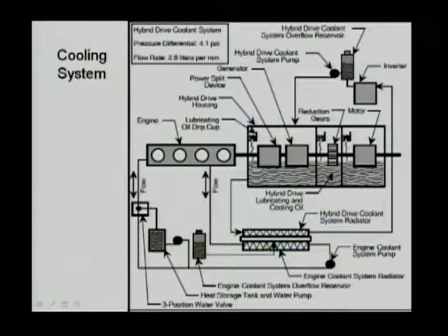But just above the engine coolant radiator, there's another radiator, even though they are mounted at the same place, but it is a separate radiator. And if you follow the arrow pointer directions, coming out of the radiator, the liquid will go through a pipe to the inverter on the top right corner. So the liquid goes to the power electronics to cool the power electronics first. So the cold liquid goes to the power electronics and cools them down pretty good